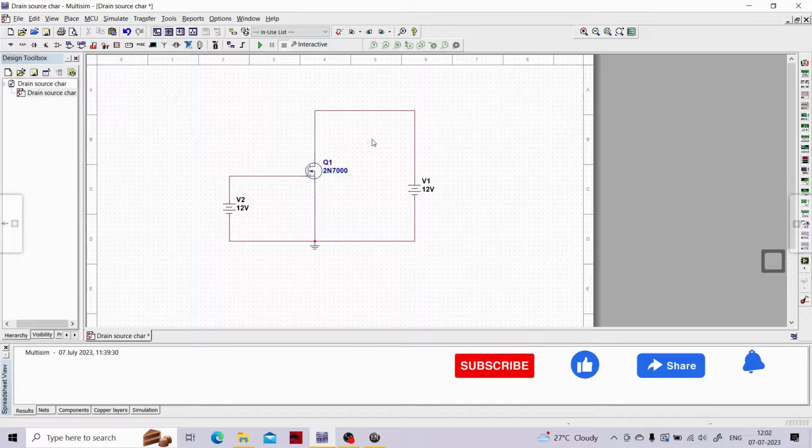Because if you connect a resistor, we won't get the proper voltage across VDS. What we are doing here is changing VDS directly, and then we are also changing VGS, and based on that we are plotting the curve, that is the output curve or the drain source characteristic curve. Great. So let me go to the simulate option, but before that let me